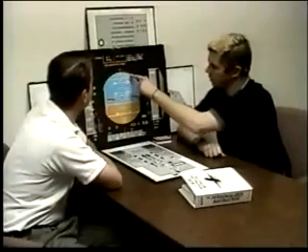When the flaps are 1, 2, or 3, the thrust is at least 1.25 EPR, and there's a 0.3 or greater difference of EPR between the two. So it's got to have an asymmetric thrust situation. So when you center up that beta target, you're getting the optimum side slip in there. Doesn't mean you have 0, it means you have an optimum side slip. Go through the scales for me. Sure, you've got 10, 20, 30, 45, and 67.